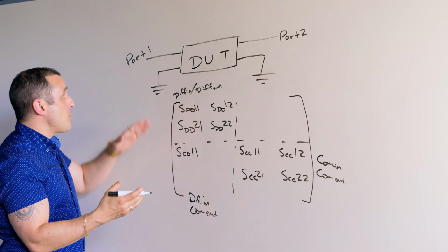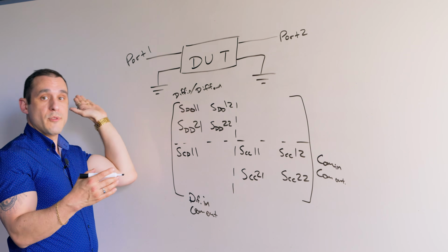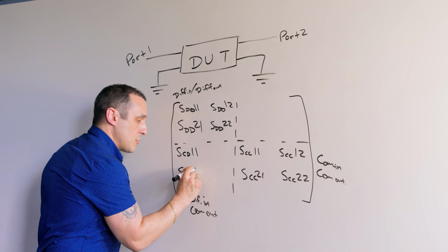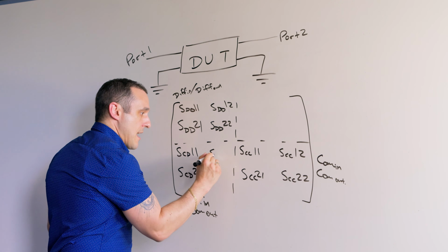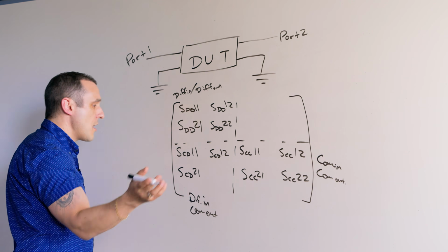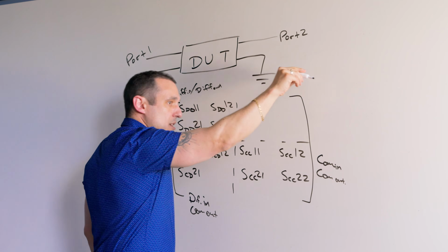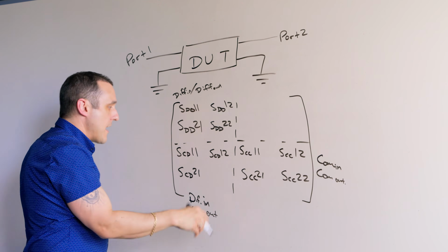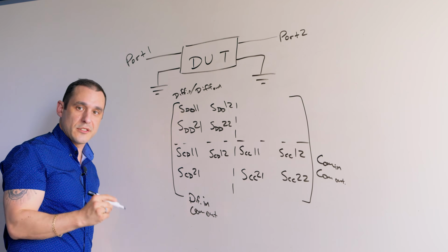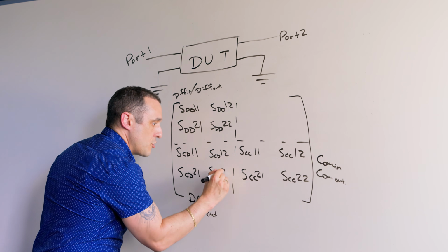In other words, I put in some differential mode signal, but some common mode signal reflects out. Here we have SCD21 and then SCD12. Again, these are insertion loss terms. I input some differential signal, I get out some common mode signal, and then that common mode signal is attenuated compared to the differential signal I put in. Then we also get SCD22.